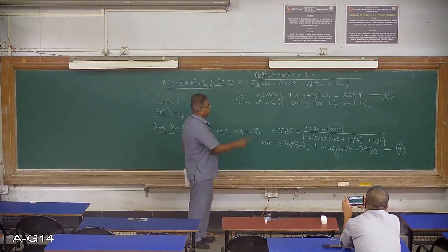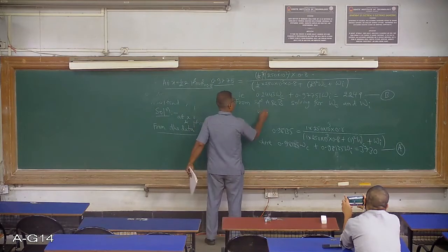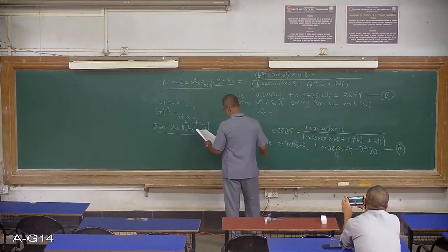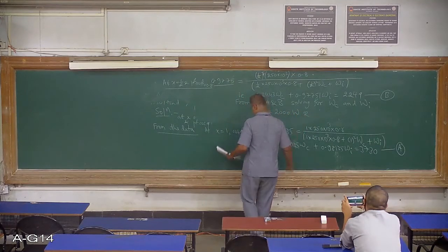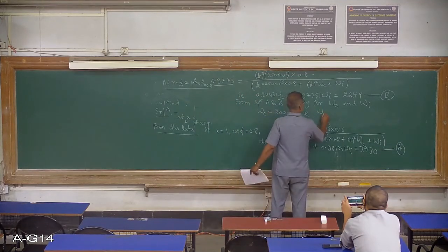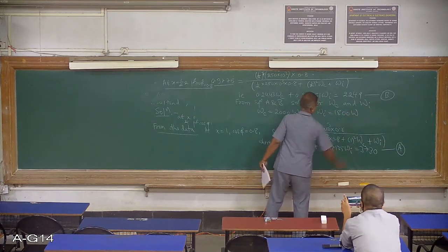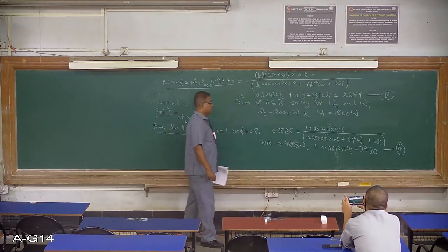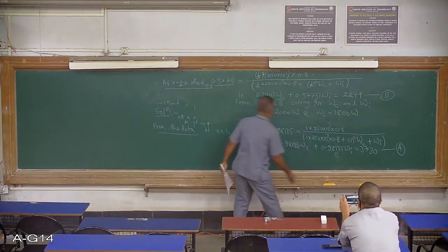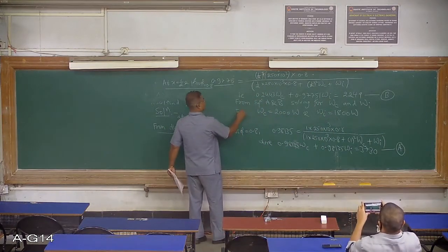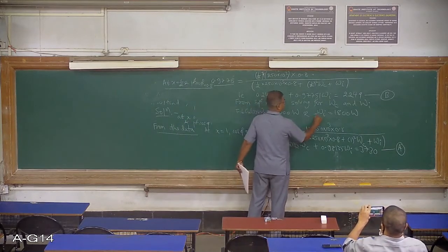On doing that, you will get the answer readily as WC equal to 2000 watt and WI 1800 watt. So in this way, we have got the values of the full load copper loss and the iron loss.